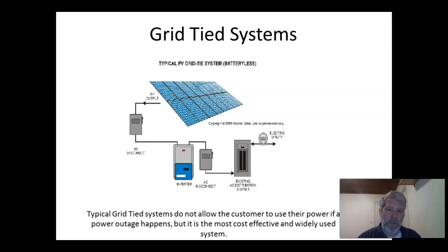But with microinverters, it's still hooked up in a very similar way physically, but instead of being hooked in series, they're being hooked in parallel. So all of your voltages are at 220 volts, or 240, and your amperage is what's getting pushed up, and you would eliminate this guy here.